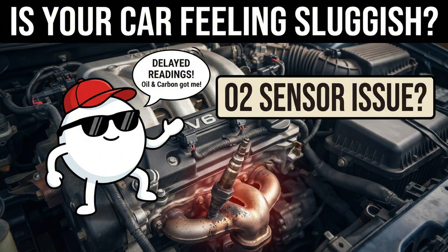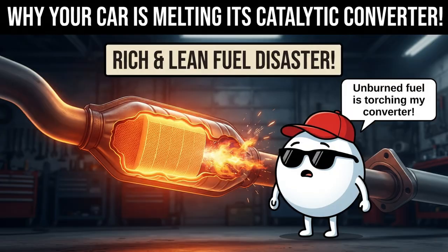If the upstream sensor becomes sluggish due to oil burning or carbon contamination, it sends delayed readings. The engine fluctuates wildly between rich and lean states, wasting gas, causing engine surging, and sending unburned fuel into the exhaust pipe where it ignites and physically melts the ceramic core of your catalytic converter.